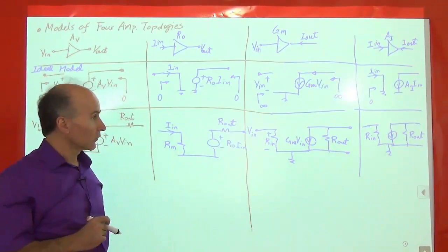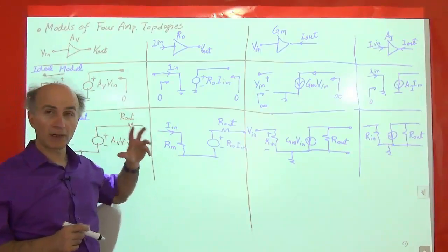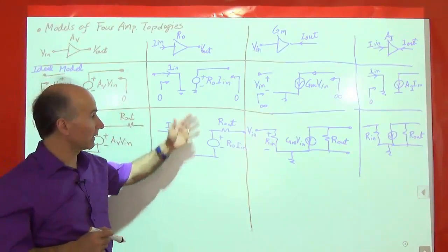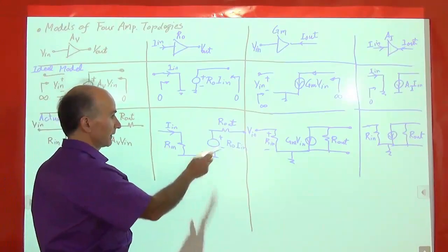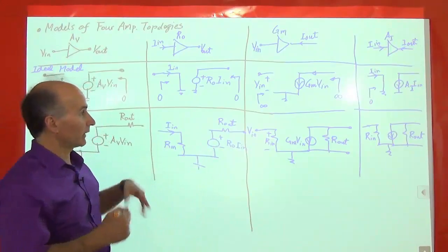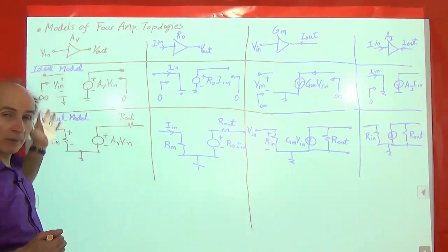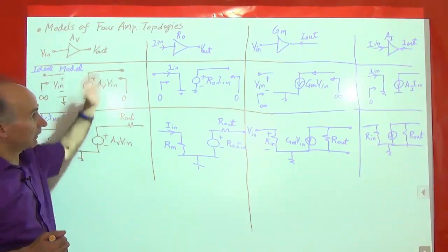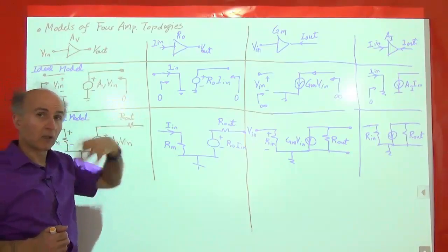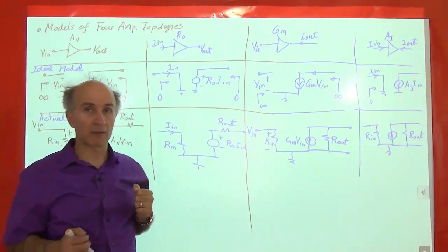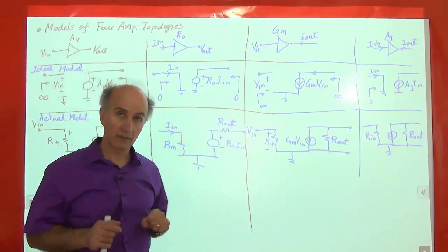All right, so it's important to remember these, and again, anytime you don't remember, just go back and check this table, and we just have to go back to the fundamentals, sensing a voltage, sensing a current, what impedance does that require, generating a voltage, generating a current, what kind of output impedance does that require, right? Based on those, you can always find these models.